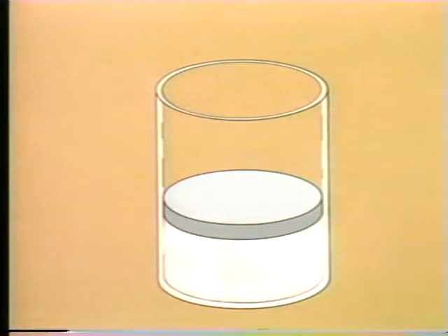The two fluids are also different in terms of compressibility. Basically, a liquid will not compress, while a gas will. To explain this, imagine a container filled with a liquid. Pick a piece of solid material, such as a block of steel, that exactly fits the top of the container, and then push down on it. The liquid will not compress. It will not be squeezed into a smaller area. If the fluid in the container is a gas, however, and you apply enough force to it, you can compress it into a smaller space. This is all that a cylinder of compressed gas is, gas that has been forced into a smaller space.